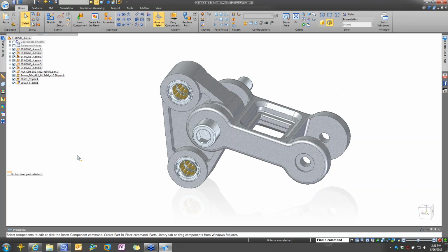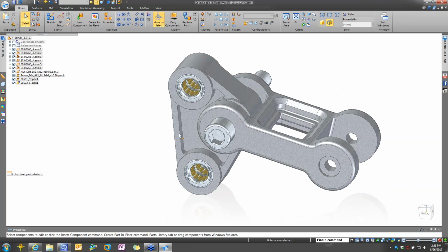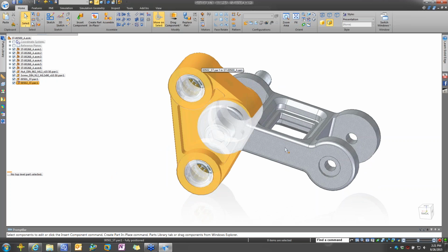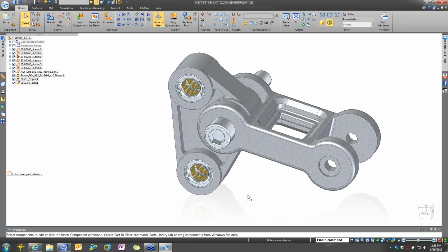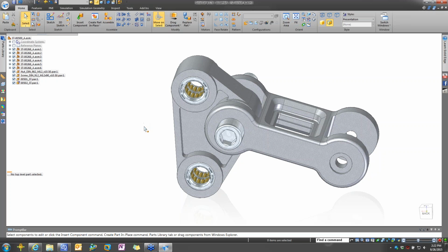So typically in a traditional CAD tool, when you want to make changes to components, you will go into the specific component that you want to change. You'll make the modification, which then reflects up to the next level up. So for example, if I want to change this part, I'm going to change it in the part, and then it's going to reflect that change in the subassembly, and then that change will be reflected in the higher level. But the user is finding themselves having to dig down to find the components and make those changes at that level and then work their way back up. And we'll do that also in this particular example, and then we'll show you some other benefits that Solid Edge has that will eliminate that step.